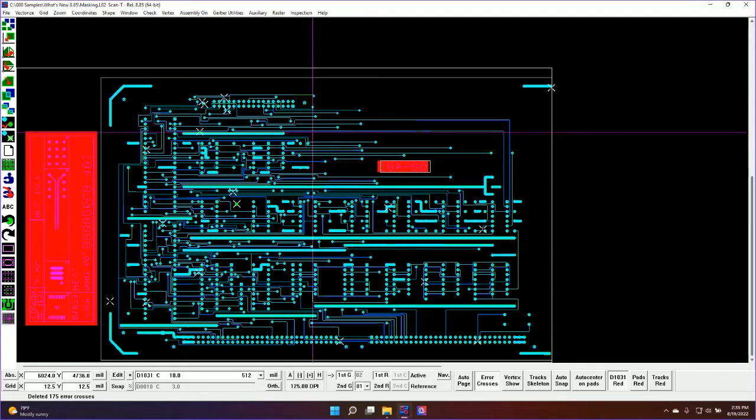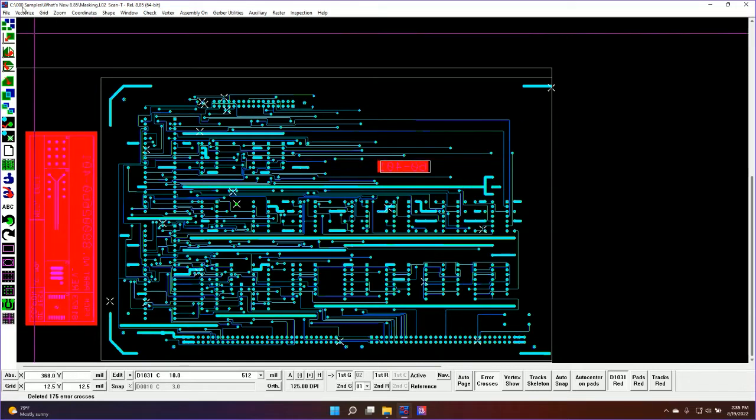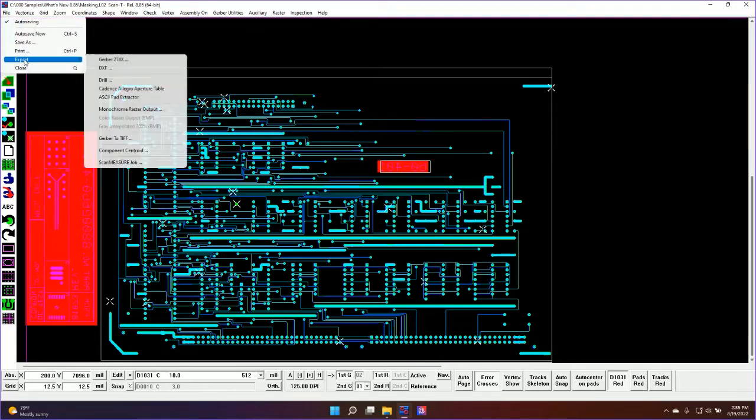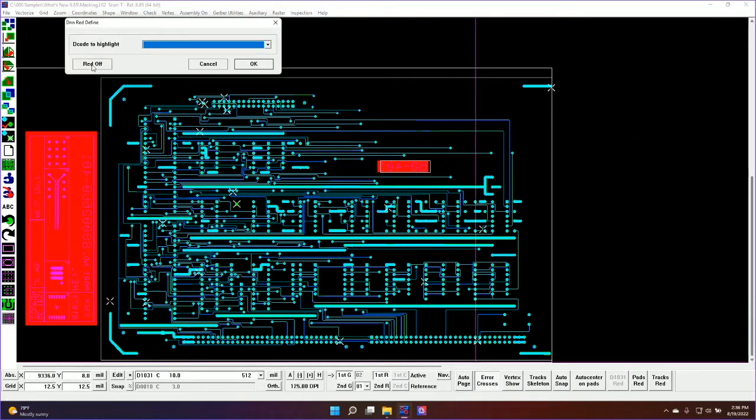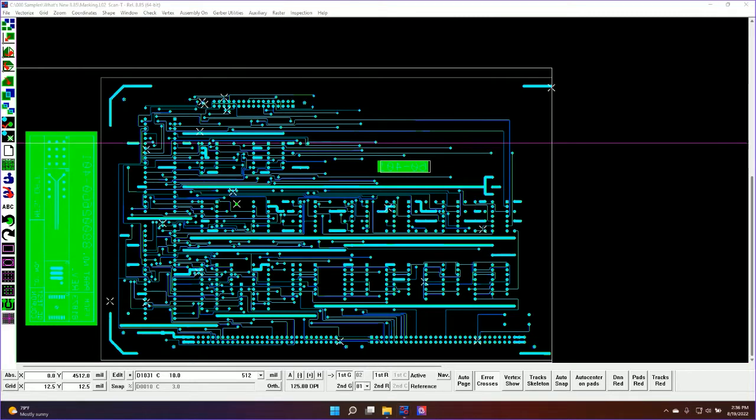We're excited for you guys to start playing with it, giving us feedback on the user interface. Again, once you've created your Gerber file that has both the inspection areas and the mask areas, all you need to do is do File, Export, kick out a Gerber 274X file, and then you can re-import this for future inspections, and that masking will always work because that D code will carry through. So that is our really major enhancement for inspection this year. Again, that's been on the list for a long time. We're excited to share that with you.